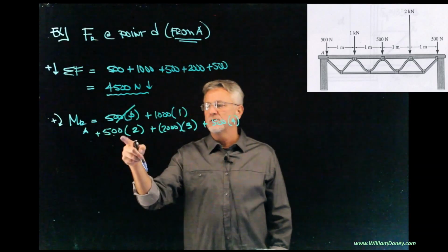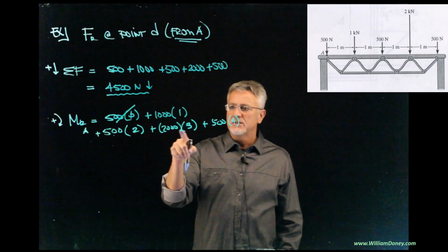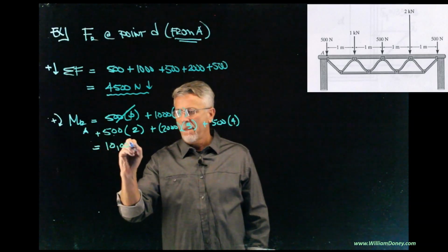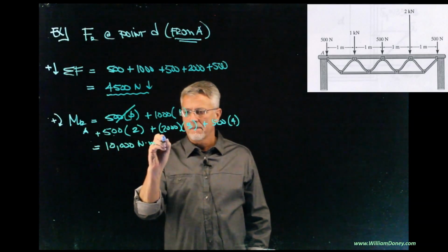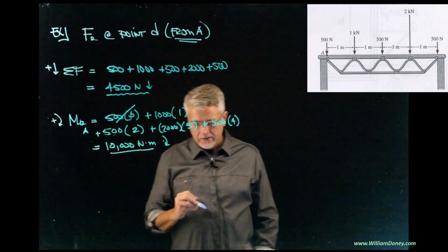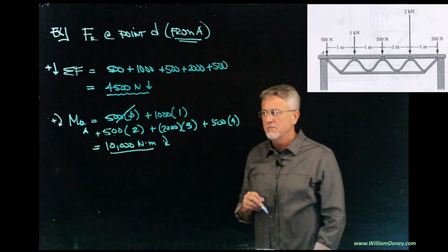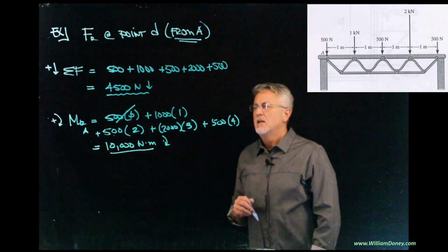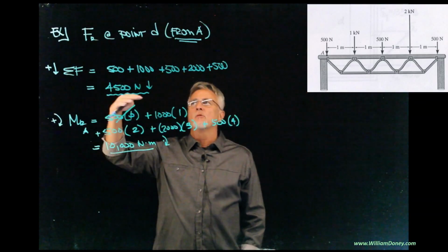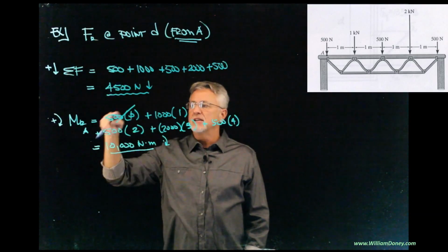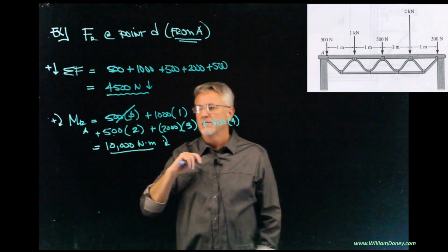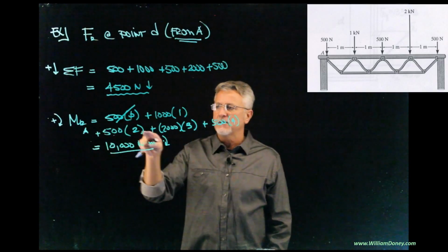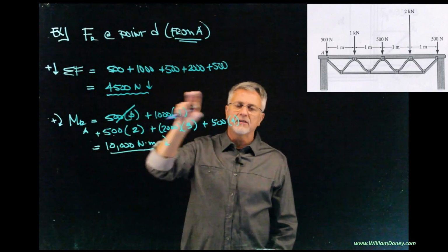So there's 1,000, 2,000, plus 6, 8,000, 10,000. 10,000 Newton meters. Okay, 10,000 Newton meters. So this would be a 4.7 solution where we go to a single resultant force, single resultant moment, done. Again, this is a free vector, so I say it's about A, because that's where I got all the generation of those distances, but it's a free vector, so we could slide it.